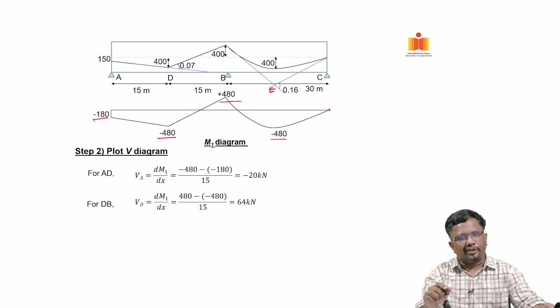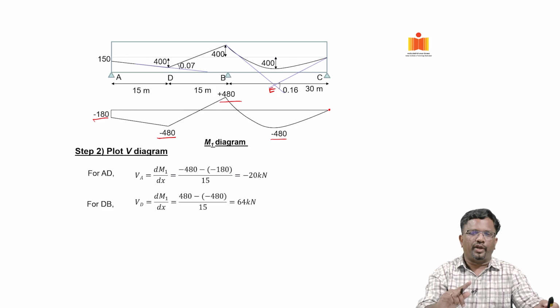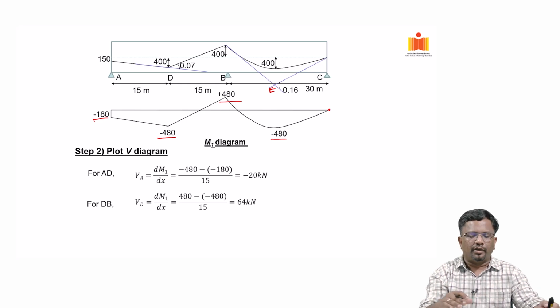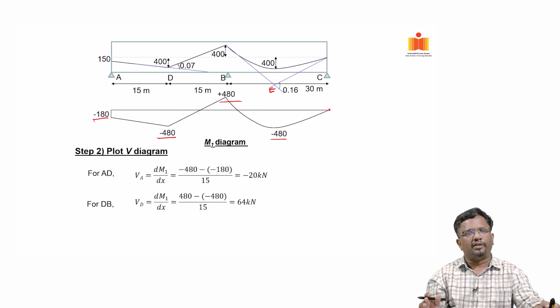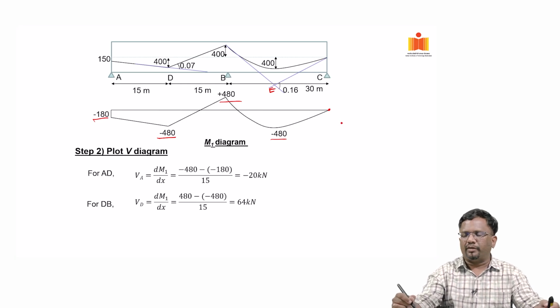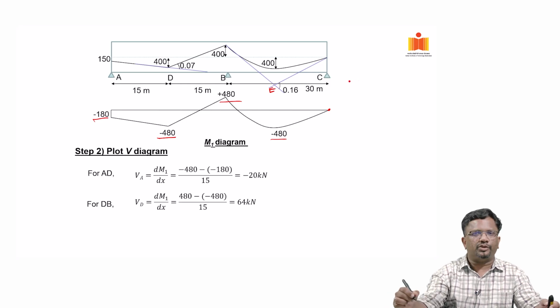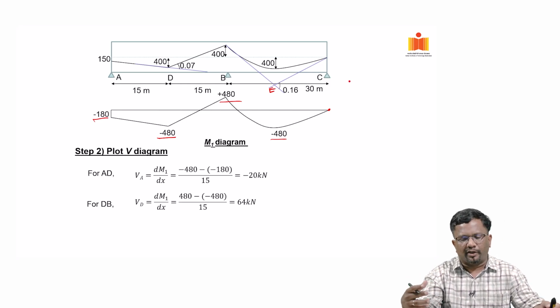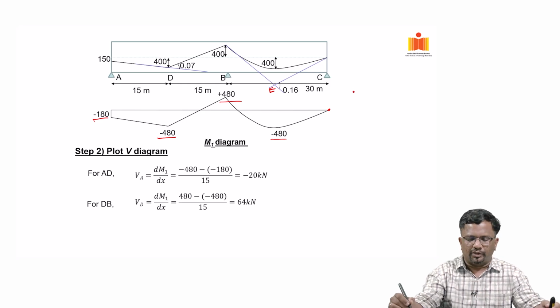Now, I want to establish the loading diagram. See, loading diagram quickly, as I told, from equivalent load also you can create, but let us say for a more generic case quickly we can generate. Now, the whole idea is we want to find the entire loading distribution, so that I can do moment distribution to find out the entire M2 diagram, which is the summation of M1 plus M1 prime directly.